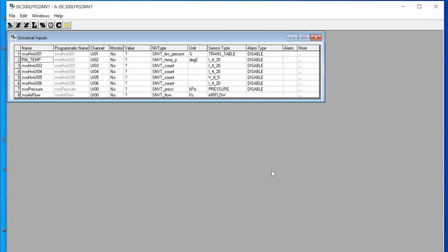Like the DDC naming, not just the variable naming, the DDC name. Then how do you organize your database? That's very important. Otherwise, after you finish, you cannot find it. You cannot remember where each DDC is, especially at a site where maybe many locations you install. Then you will not be able to find it.